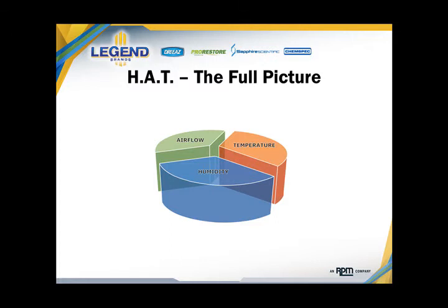For example, a good rate of air movement across wet surfaces and a high or warm temperature to support drying with no control for humidity is a disaster waiting to happen. If we had air moving across surfaces at a very high rate of speed and the temperature was warm enough to support the drying process, but humidity was saturated at 100% relative humidity, then all we're doing is transporting wet air throughout the drying environment. This is a catalyst for secondary damage, at a warm temperature and at a very fast rate.